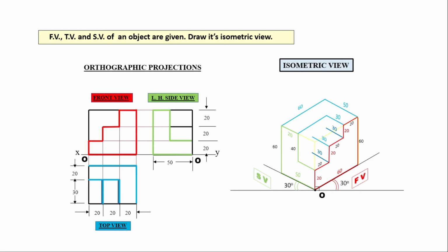Now again we come to the front view, because behind this line there are some lines that will be visible from the front view. Okay. So here again the lines will be overlapped. We'll start from this point. That point should be here. From this point there should be a vertical line, so we draw this vertical line. Then you can simply join these 2 points.